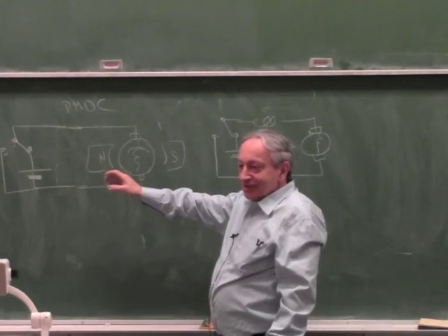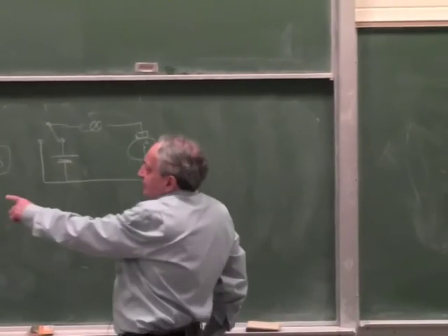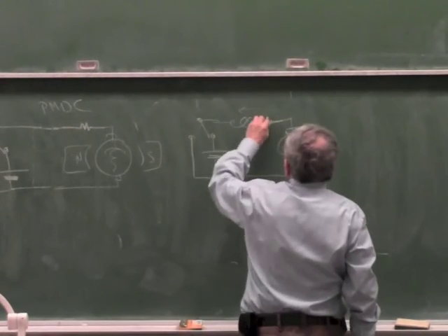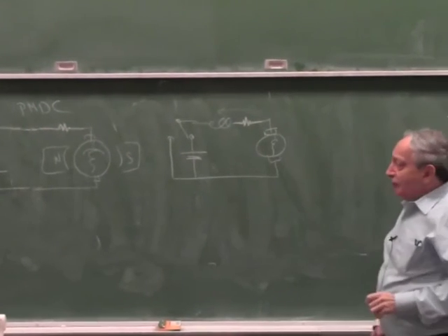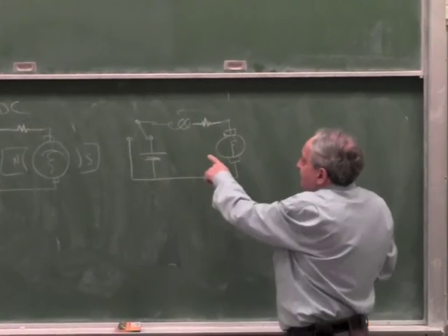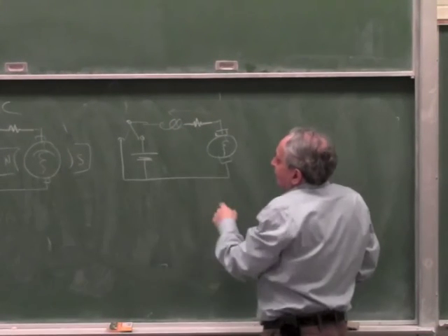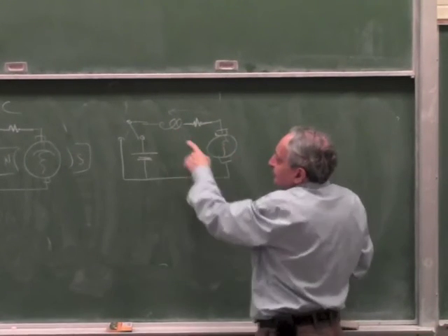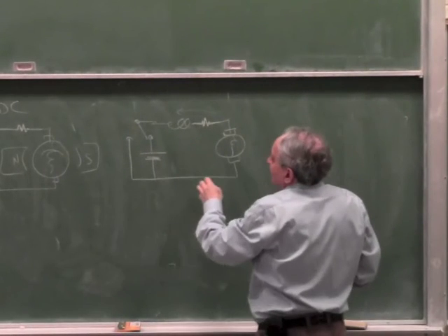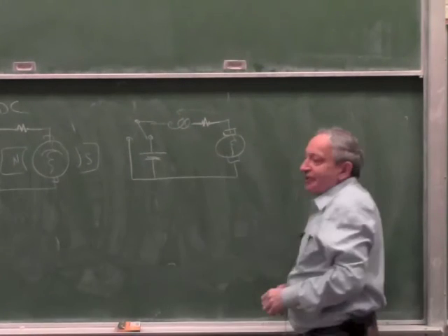Okay? And okay. Now, remember the model of all these motors, the current is not infinite, because there's also some resistance. So this will be much less efficient in braking. If you want to make this efficient in braking, you really should supply some current to this when you brake. You should short the armature but supply current to the field. Okay? So say if you can short the armature but use the same battery to power the field, it will be much better.